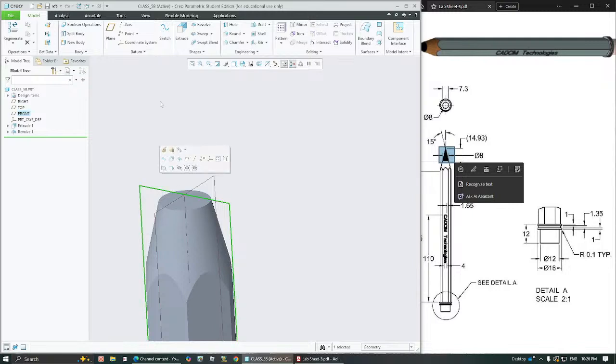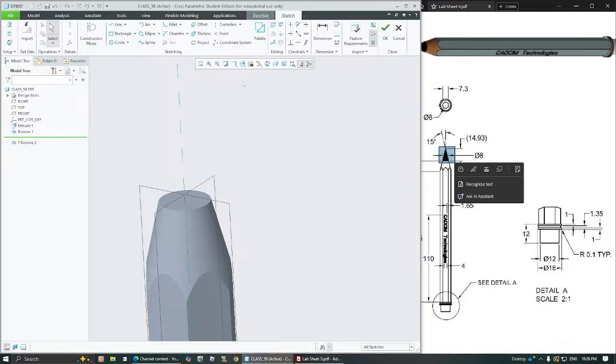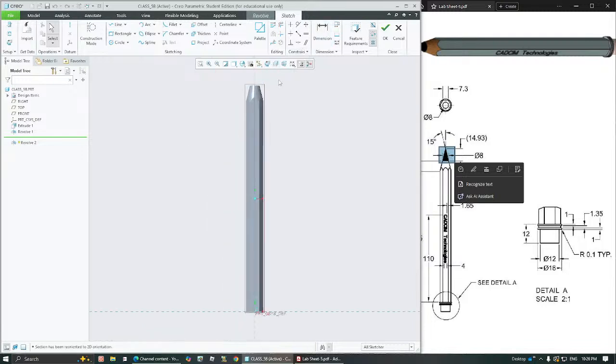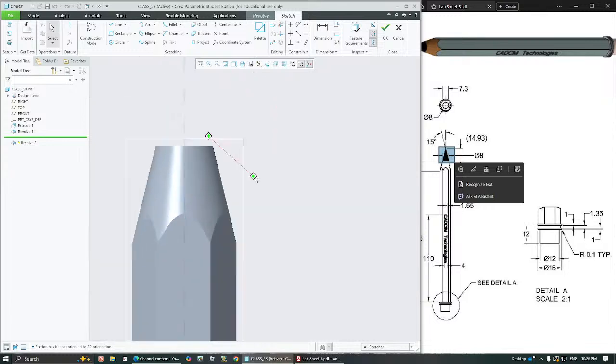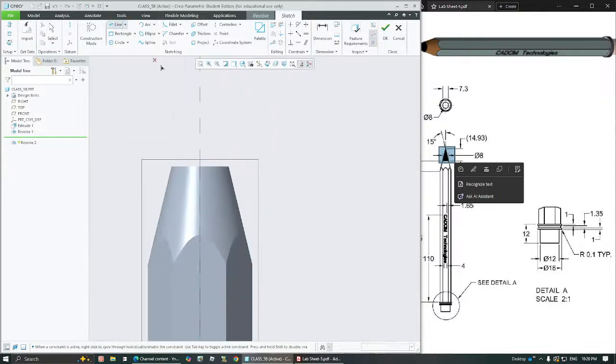So let's go ahead for this plane once again, go for revolve, and once again make it normal. You can just expand by clicking Control and mid mouse button and choose line.